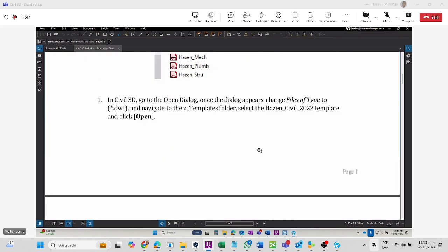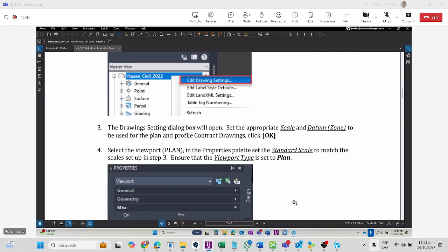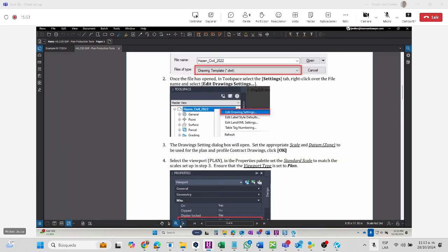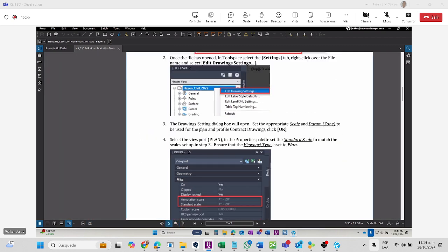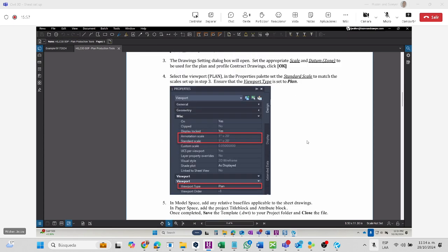Now, you're welcome to create sheets individually, just by opening a drawing and doing a save as and zooming in and out to your viewport or whatever you want to do. But this process allows for an automatic creation of sheets with views, alignments, basically allowing you to produce multiple drawing files and add them to a sheet set in a simple process.